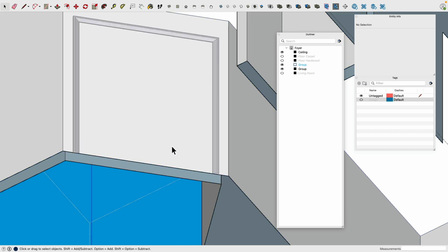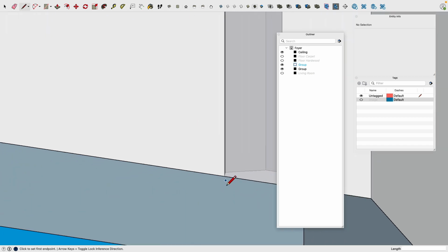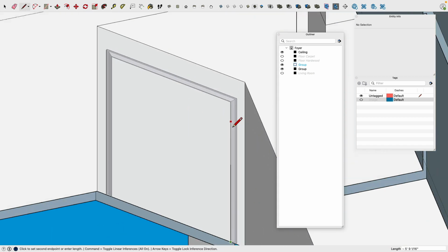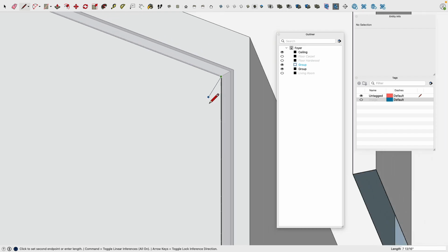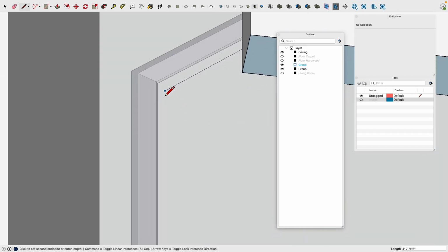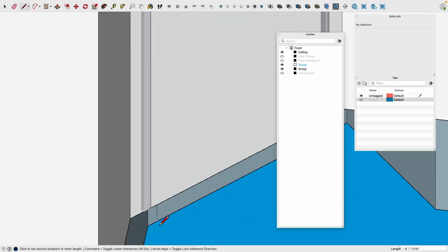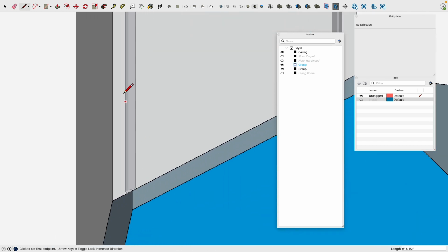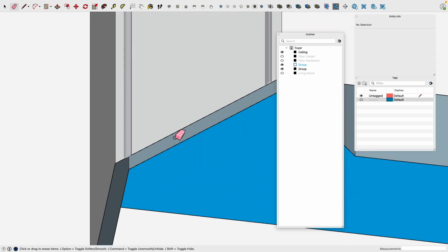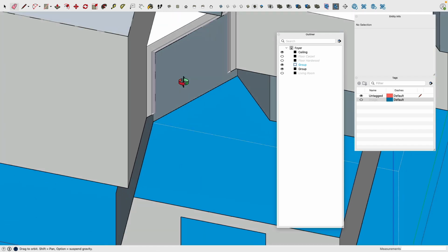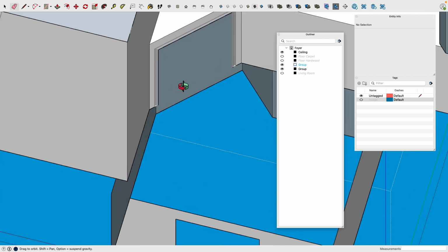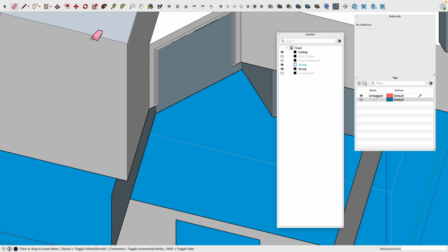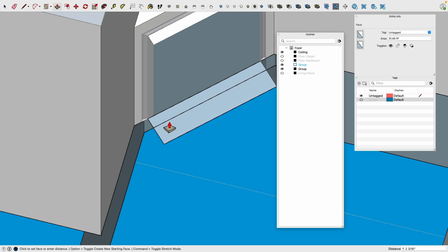Okay, let's do this. So double click onto the wall, line tool, and then very carefully where this intersects, sits rather on each other, I draw these lines. Cool. Then let's delete this one. There's the opening. Okay, how do we get to the other side? Let's actually undo this step and see via push and pull. Can we do this? Yes, we can.